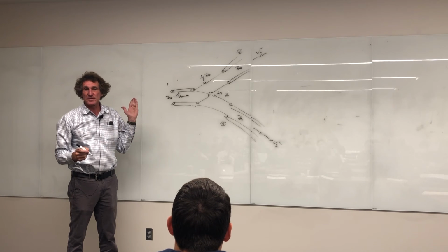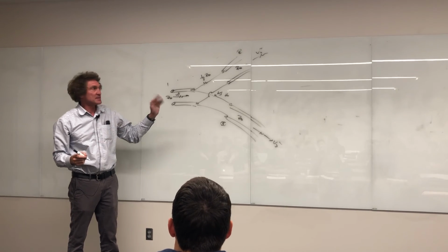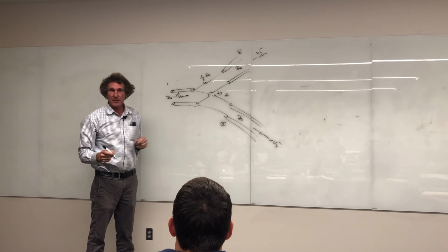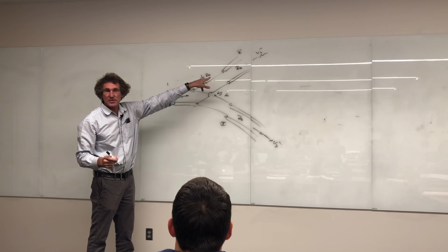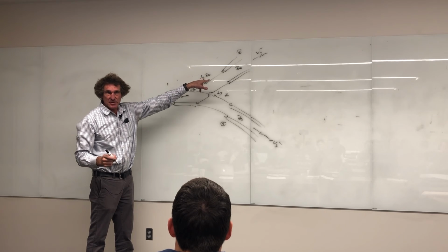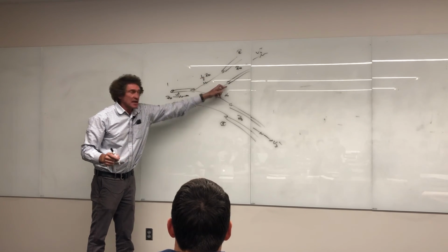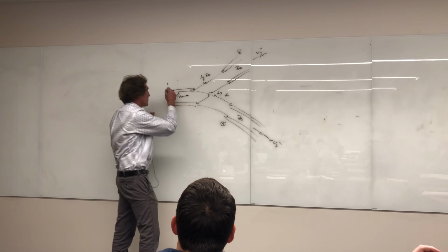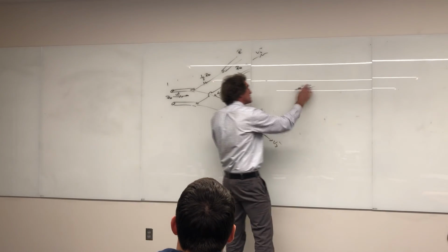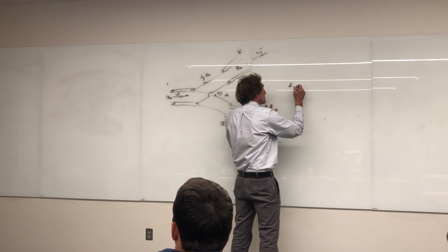The problem with this design, and I'm going to show you its impedance match, is you're losing power here and here. You follow me on that? That's 1/3 of an ohm, that's 1/3 of an ohm. These are very short lead lengths, so you don't have to worry about that being a transmission line in there. And this is just taking that and grounding that, taking that and grounding that to there. Now, what's the input impedance looking in port 1? So what is Z in looking in port 1?